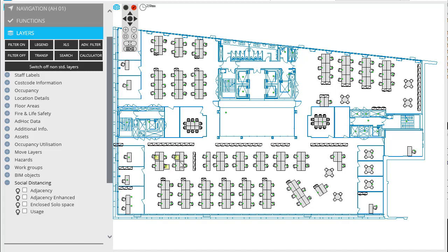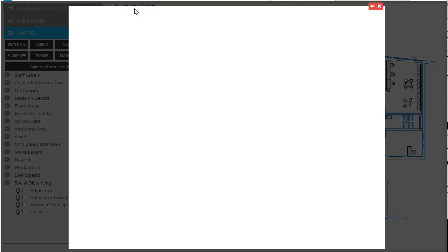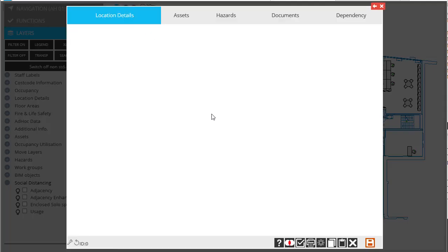So I'm just going to use the shift key to alternately pick these in a checkerboard fashion. So it's not too time consuming, but it does take some time on a larger floor obviously. And then we can use the multi-edit. So this is standard functionality.